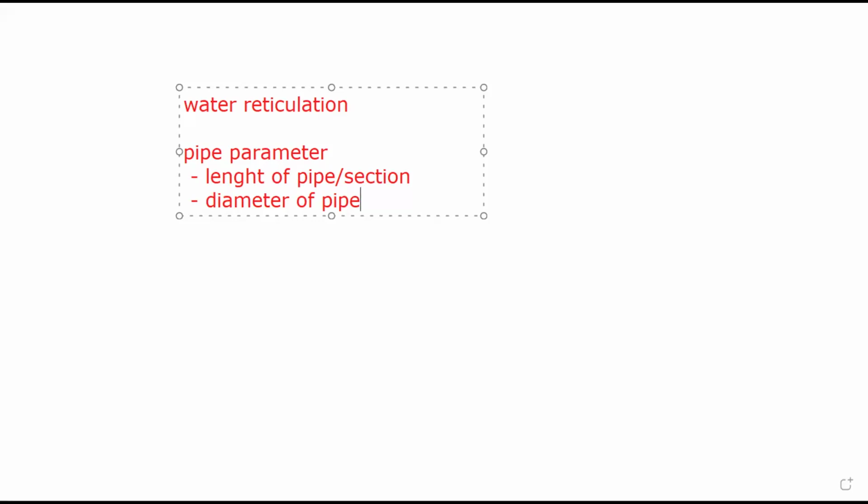And as a rule of thumb, from my experience as a consultant, not just as a trainer, if you are designing any estate layout or any city layout, please, your minimum pipe design should be 75 mm, 3 inches pipe. I've seen people using 2 inches pipe. It is absolutely wrong. Quote me anywhere.